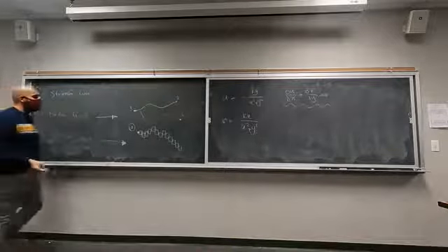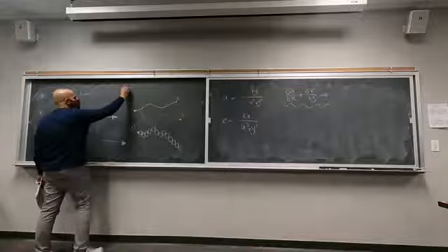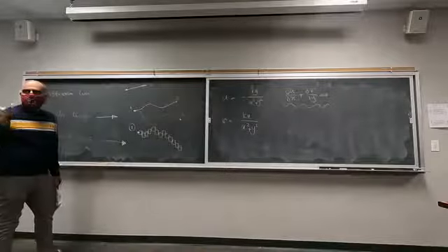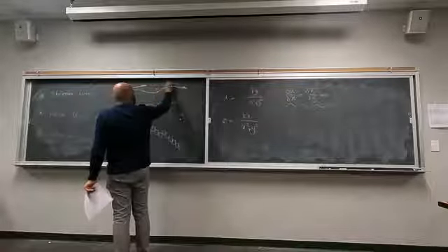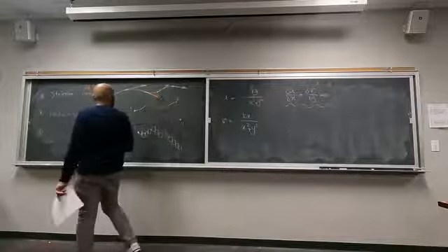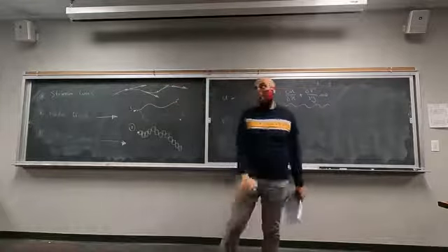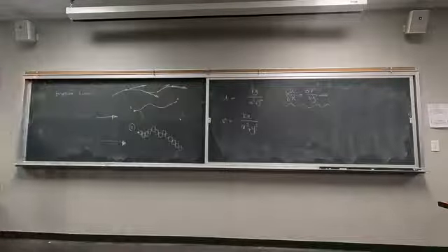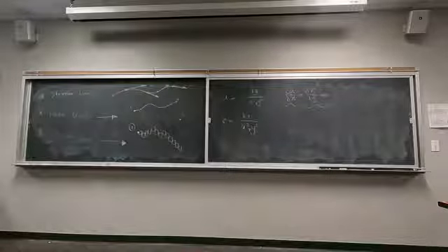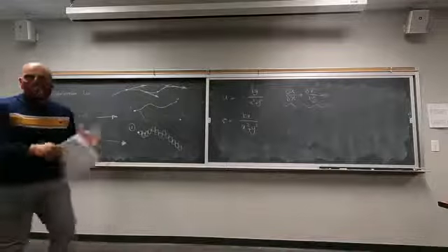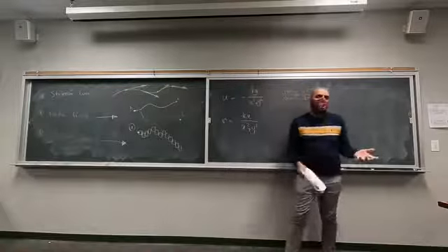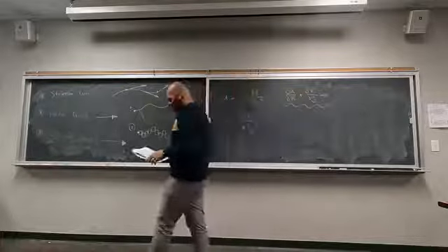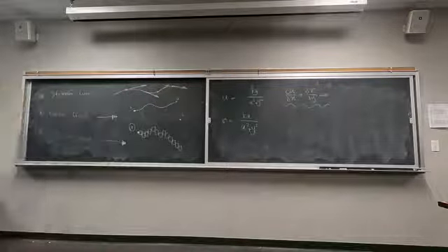A streamline is a line that is tangent to your velocity vector at all times. So if your velocity vector is changing, is moving, this line is also moving. And a streamline is a concept that we are going to use a lot in aerodynamics. What will happen is, if you are dealing with a steady state condition, with a steady flow, so the changes over time are zero, then all of these three are going to essentially be the same for a steady incompressible flow. Okay, are there any questions about this definition?